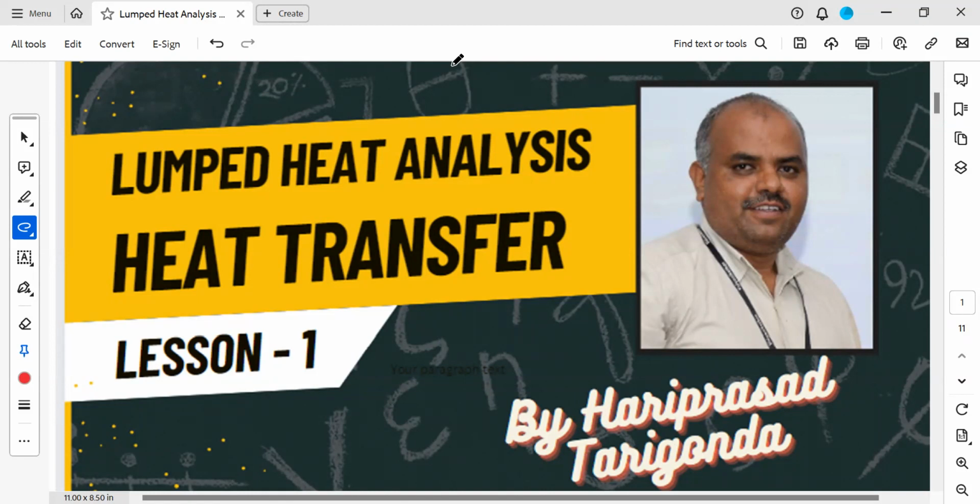Examples of temperature variation with time: one is the heating and cooling of the earth's surface, which happens during daytime and night time, so the temperature varies continuously with time in a day. Similarly, in an IC engine, due to combustion and cooling of the engine cylinder, the temperature of the cylinder surface varies continuously with time. These are two examples of transient heat conduction problems.